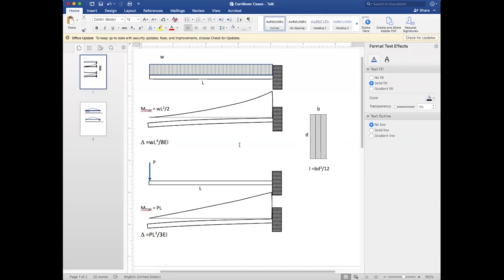But I knew I had put in extra forces, so the safety factor that I was using was considerably higher than would actually occur out at the job site, especially when the beam was not loaded. Another issue with LVLs is that they can be fabricated to be considerably longer than sawn lumber.